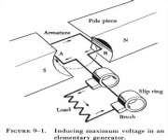The terminal voltage of a shunt generator can be controlled by means of a rheostat inserted in series with the field windings, as shown in figure 9-16. As the resistance is increased, the field current is reduced. Consequently, the generated voltage is reduced also. For a given setting of the field rheostat, the terminal voltage at the armature brushes will be approximately equal to the generated voltage minus the IR drop produced by the load current in the armature. Thus, the voltage at the terminals of the generator will drop as the load is applied.